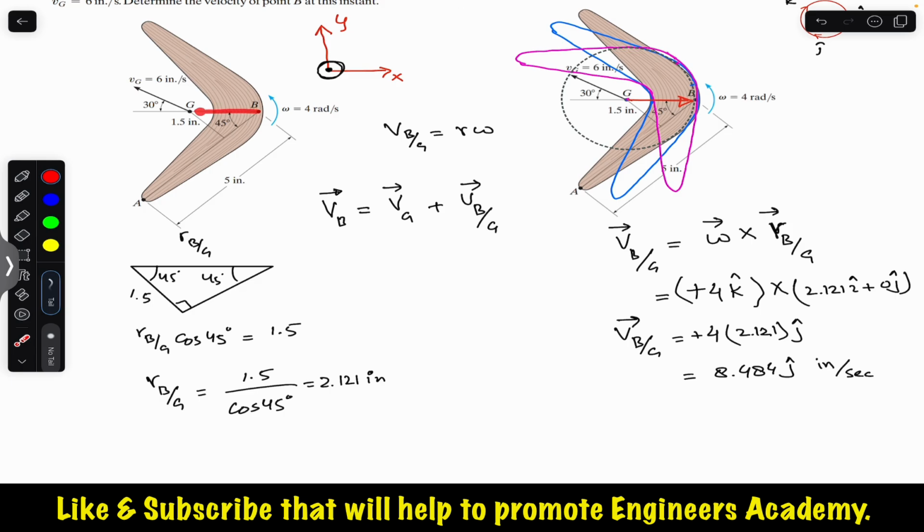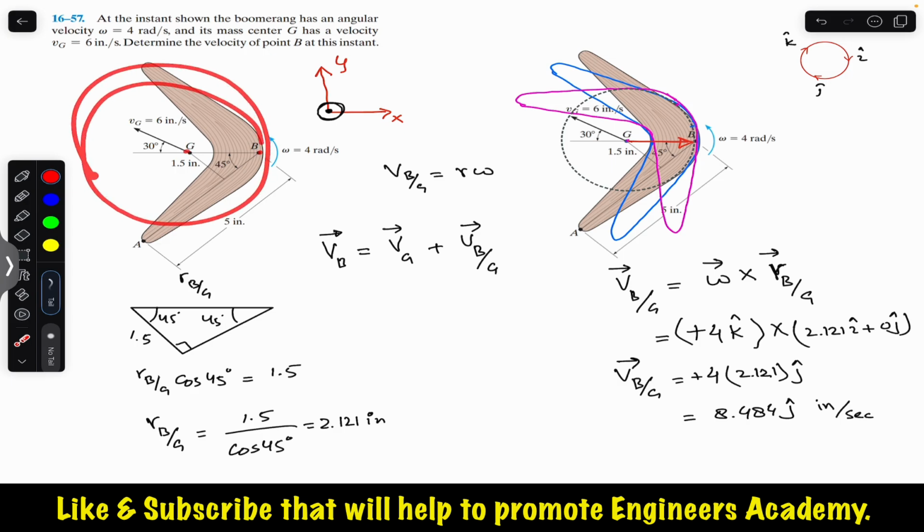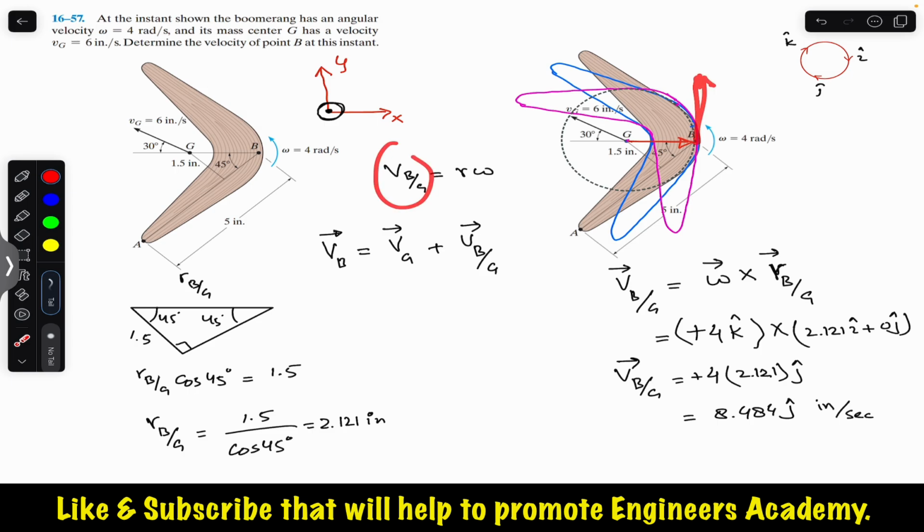So 2.121 into omega, we got 8.484, and the direction is in the positive J. Since we are thinking of the velocity of point B relative to point G due to that circular motion, this velocity will always be tangent to the path of point B. Since point B is moving along the circular path, the direction of this velocity will be tangent to this path. So at this particular instant, the direction of this VBG will be in the positive Y direction.